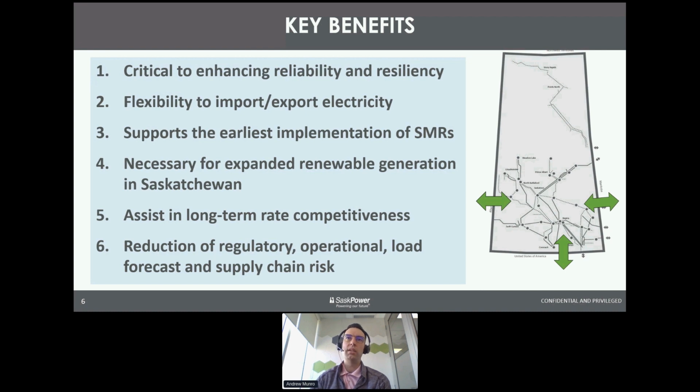And what we've done this year, just as of April 1st, is we've implemented quarter-hour scheduling. So we can schedule electricity on 15-minute intervals. That means that if, say, the wind's blowing at 10:05 and then dies down, we don't have to wait till 11 o'clock to bring in electricity or move it out. We can do it at 10:15.